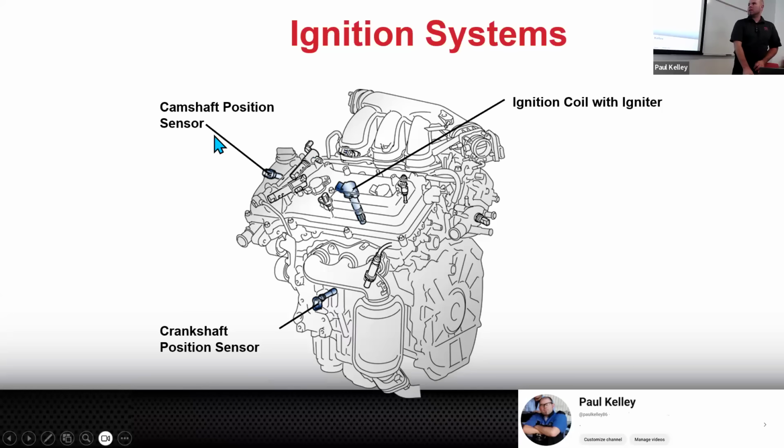So yes, you could unbolt the 10 millimeter in this coil. You could slide it out. You have to keep the primary wires plugged in, and then you can crank it, and this sucker will spark to whatever ground is nearby, right? As long as it's near a ground, you'll see a little arc, a little lightning from the coil to the valve cover, to the bolt, or to something, and be like, oh yeah, that coil's firing. Do you think that measures the voltage accurately though? It's a good way to know if the coil's firing at all or not, but it doesn't give you a really thorough and complete picture.